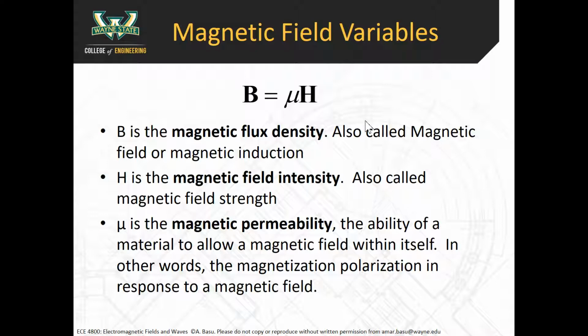Okay, when we talk about magnetics, what we'll find is that if you have a magnetic field in space, that magnetic field can become concentrated in areas where there's high magnetic permeability. So high permeability materials can act as flux concentrators, if you will. For now, just assume it's a constant. It depends on the properties of the material. We'll come back to that later and look more at what determines the magnetic permeability of a material.